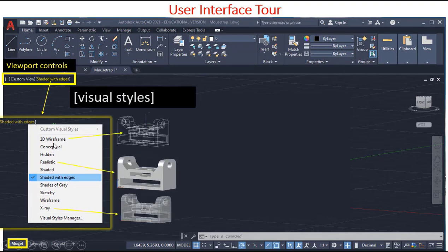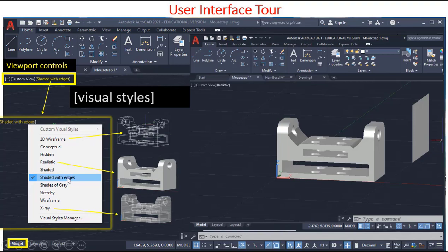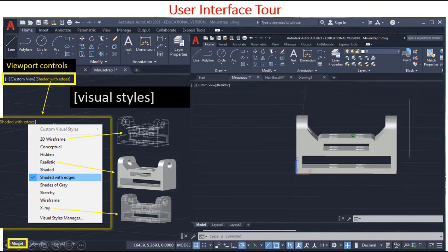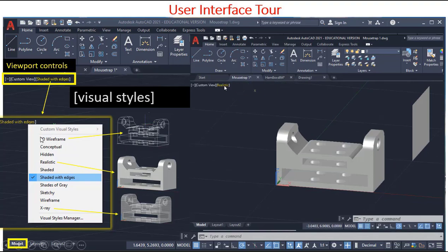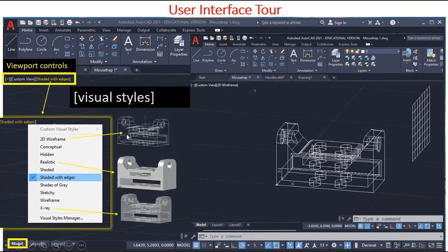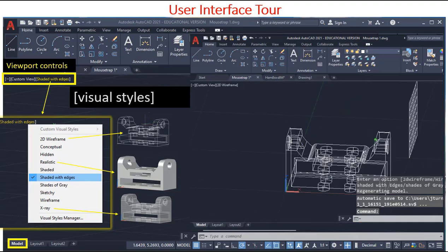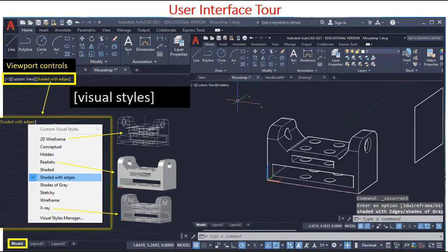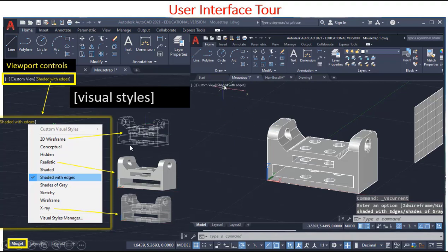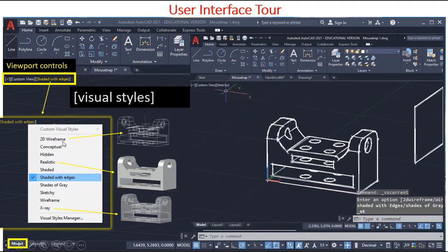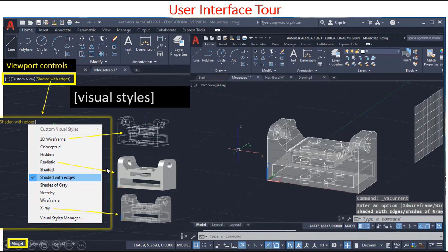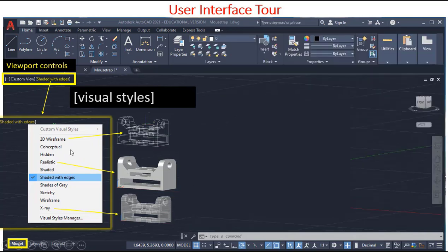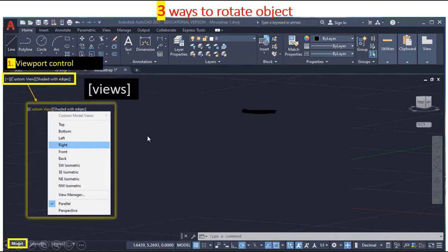So here's visual style examples. You can have a wireframe, realistic, X-ray, and depending on what you're making, one of these. I do like to come back to the 2D wireframe. You can make surfaces or solids, and knowing whether it's just a very thin eggshell surface, or did I make a solid piece when I did this 3D object? That will show up as different styles in your 2D wireframe. That's an important thing to know. And then realistic versus, yeah, so play around and you just click on the text in here, and then you can click on some different visual styles to play around with it.